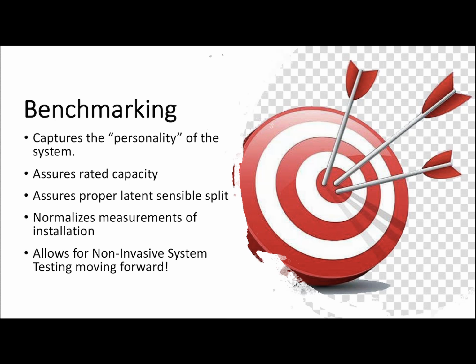It captures the impact of the filtering system you have. But what it does when we benchmark that system, we want to assure we're getting that rated capacity, we got the proper latent sensible split, and it's going to normalize all those measurements for the installation. And this is going to allow us to do non-invasive system testing moving forward. And that's probably one of the coolest things we can do with measureQuick.